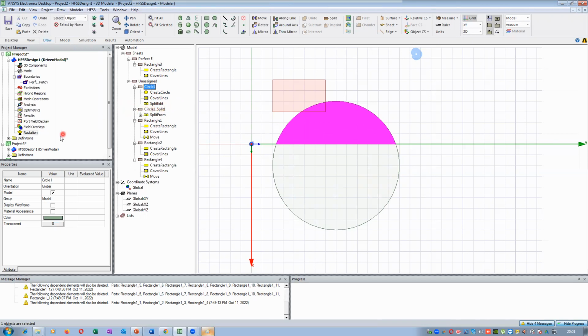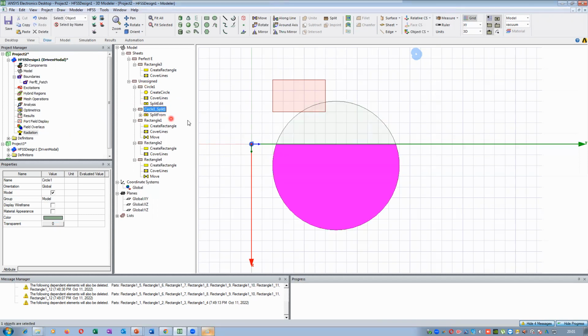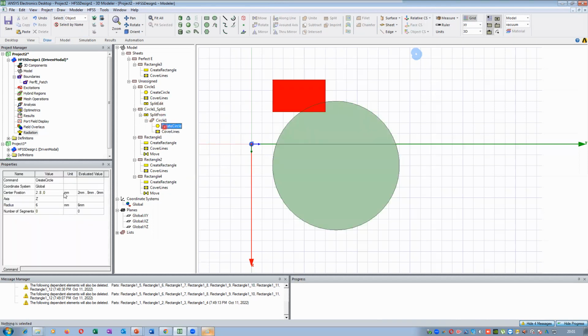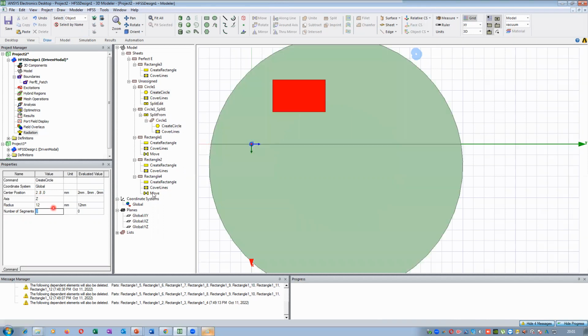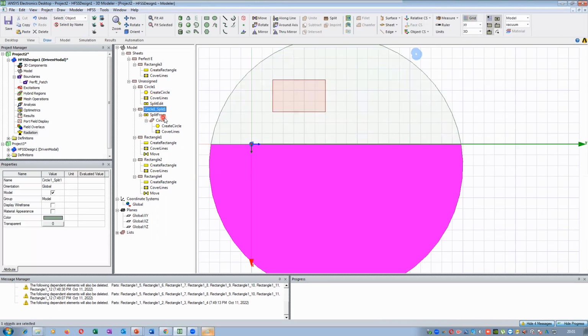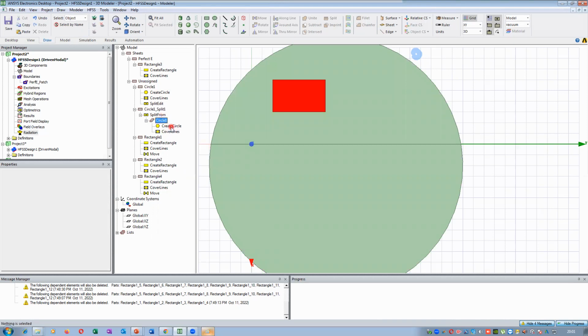So already we have given that point. So circle 1 split 1, so this is the remaining part. So in this, the command is split from, here split edit, here split from. So split from what? Circle 1. So if you want to change these parameters, suppose this parameter circle position 280 and the radius is 6. Let us take the radius as 12. Then also split exists. Now this one and this one, dimensions are changed. We can do.